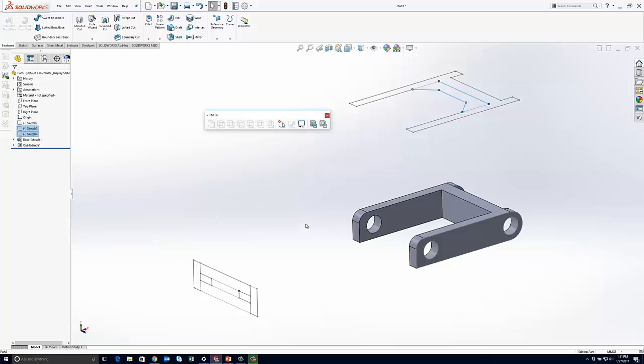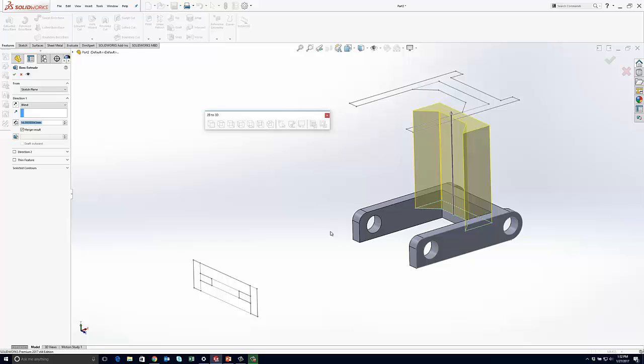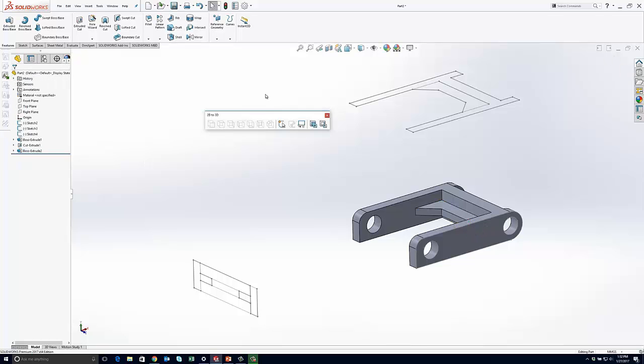Now that I got everything selected that I want, I'm going to tell this to go ahead and convert to an extrusion. Now you can see that what that does for us is it allows our extrusion to actually start at a different plane or a different level there. So we'll go ahead and use our depth once again, pick our entity, and we can see once again after about the 6th or 7th decimal place we trail off and have a little bit off in our dimension. We'll just go ahead and accept it the way it is, and that builds our part for us.